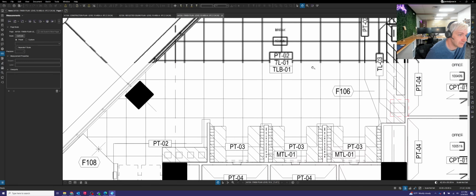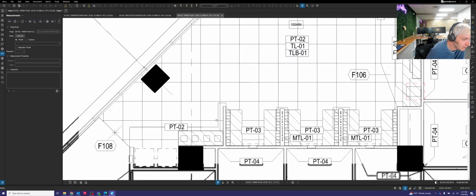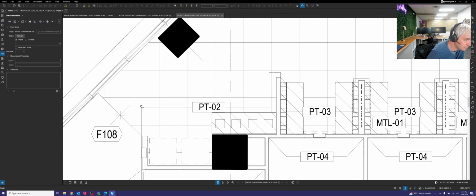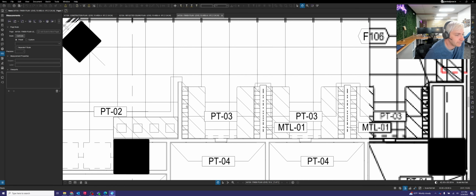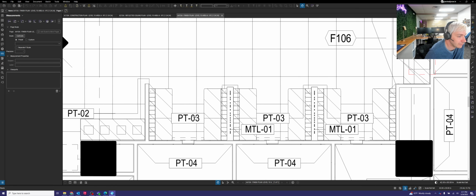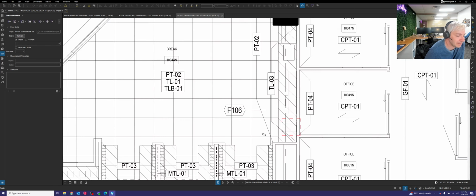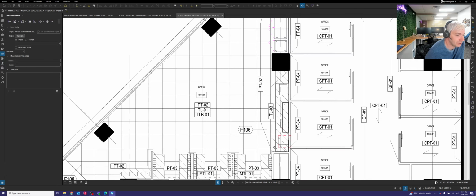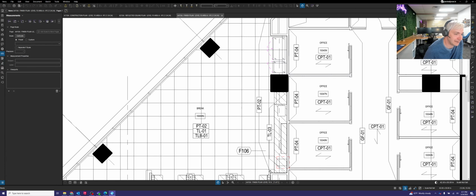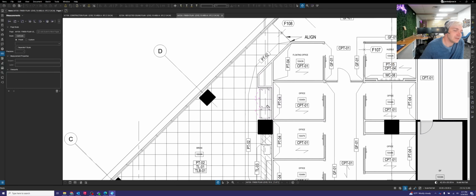So in addition to this generic note in the middle of the room, you can also see that they have this line coming up here, going around and over to here. They're saying any wall that's between these two lines is going to be finished with paint number 2. And it looks like anything past that point, we got paint 3, paint 3, paint 3, and that's going to be pretty consistent across the rest of that room until you get to here where it switches back to paint 2.